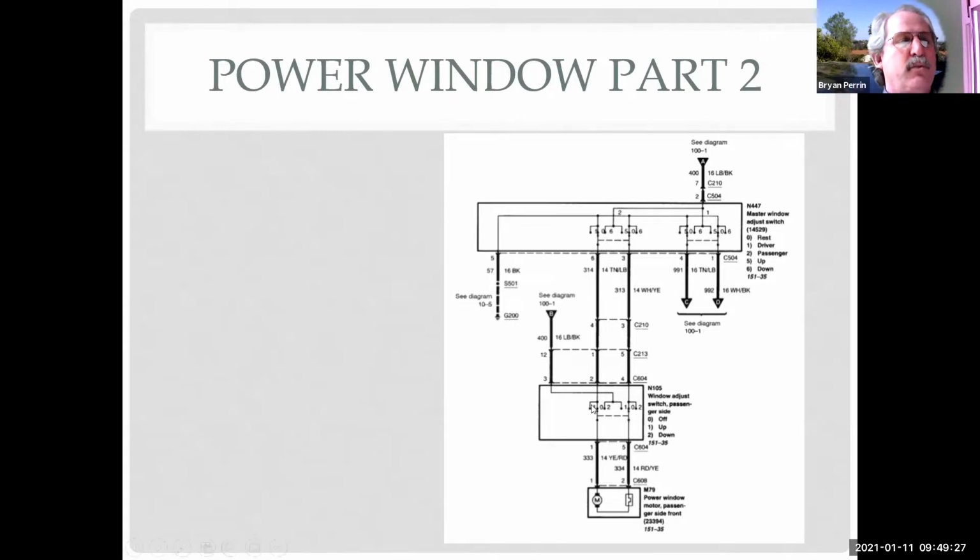So if you notice, this switch is hooked up kind of funny here, isn't it? What it does is it's going to shift over, and as we move this switch, I'm going to put power here and ground here, or power here and ground here. So you can see we have two poles here. That's why I have power coming in the middle, and I have ground on both outsides. As we slide this switch across, I can connect between here and here on 1 and 1, or I can connect here and here, 2 and 2.